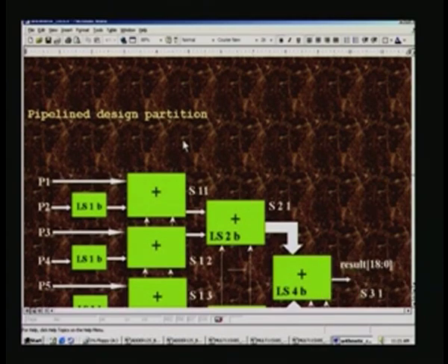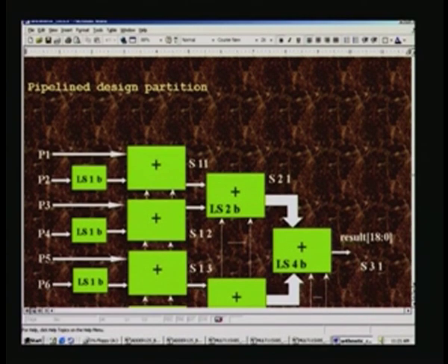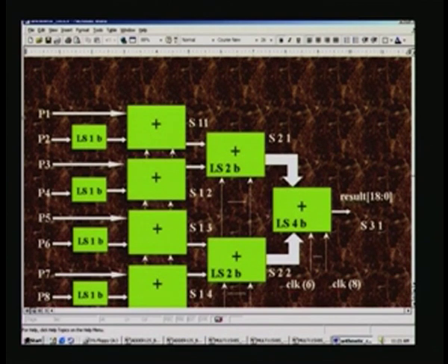This algorithm goes like this, it is pictorially depicted, and we have once again used bit partitioning as well as functionality partitioning. Here also the functionality will be basically add or subtract, and this is once again in 3 stages as we have seen with the adder before. The only extra thing coming here is that we need to do left shifting, either 1 bit or 2 bits or 4 bits.